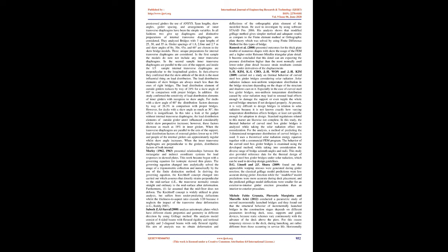Bridges used in the analysis were assumed to be composed of single spans with about 30.5 m, 100 foot, span lengths. The chord length was set at 30.5 m for all bridges, steel girders, and a 203 mm, 8 in, reinforced concrete slab. The finite element analyses consisted of a three-dimensional idealization using simple beam elements to model top and bottom flanges of the girders and plate bending elements modeling the girder webs and the slabs. The analyses revealed that this simple modeling could effectively be used in analyzing curved bridges.